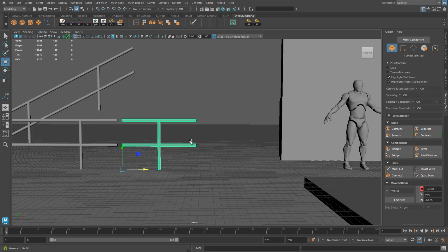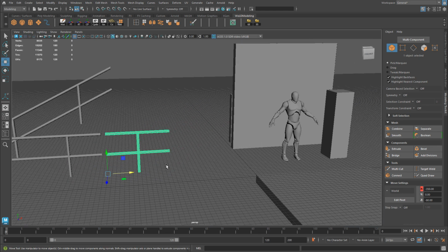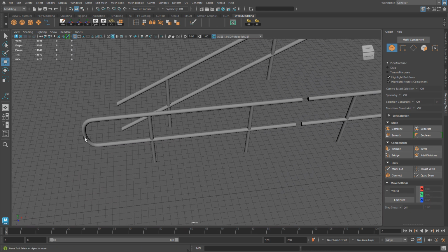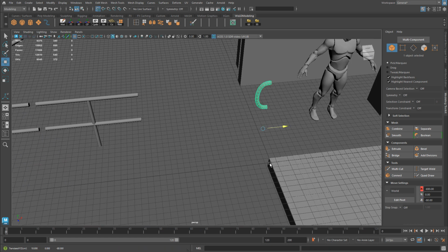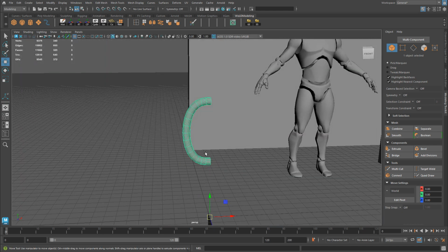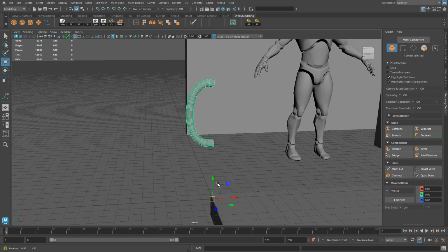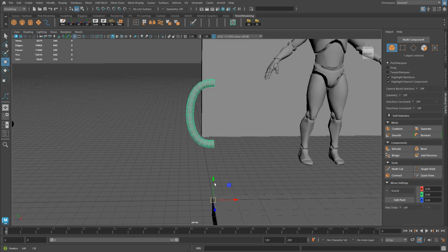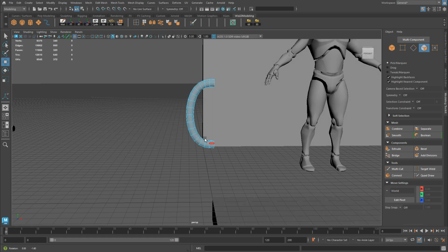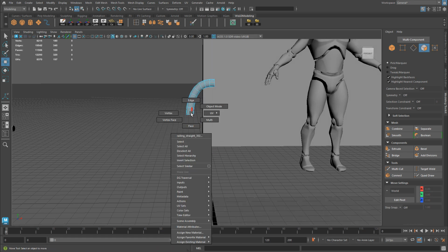Let me delete this. So just as a quick example, I'm going to make a duplicate of this end cap. Control D. Let's place it back in on the grid at our working area and at the world origin. So if I wanted different variations of this, I could actually take this because I know this railing works. This end cap piece works now. I could just delete the faces, maybe at a halfway point.